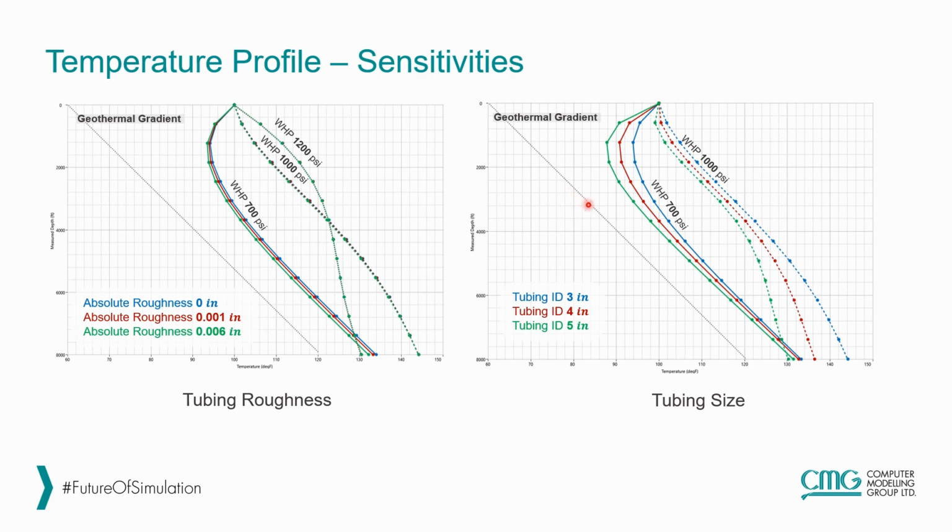So two phenomena are happening at the same time when we are increasing the tubing ID. At the bigger tubing IDs, we give more space, more room to CO2 for compression. So CO2 is being compressed less. This means less increase in temperature.